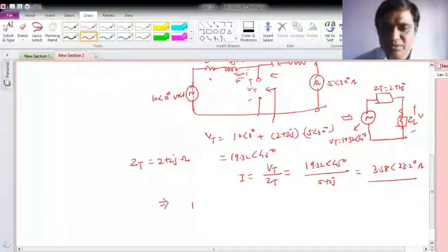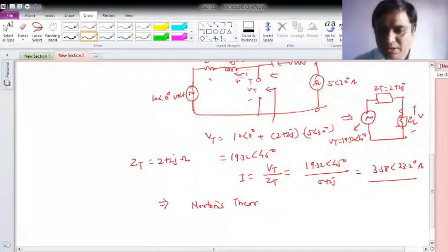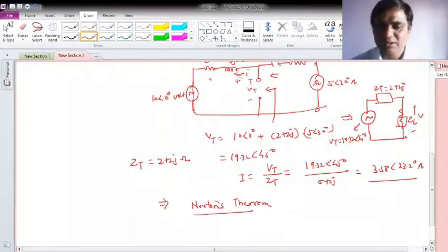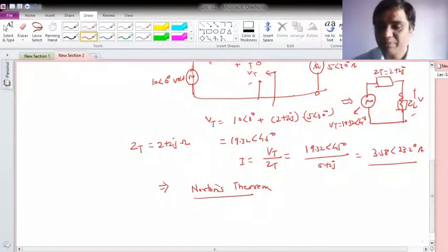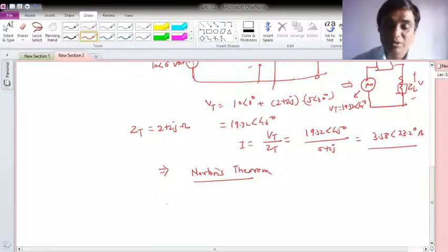Now next theorem we'll see is Norton's theorem. So basically Norton's theorem is the dual of Thevenin's theorem. This also can be used when I am interested to find a particular voltage or particular branch current or voltage. Okay. So let me tell you first Thevenin's. In Thevenin's theorem, it consists of a voltage source in series with the equivalent impedance, whereas Norton's is the dual of the Thevenin.